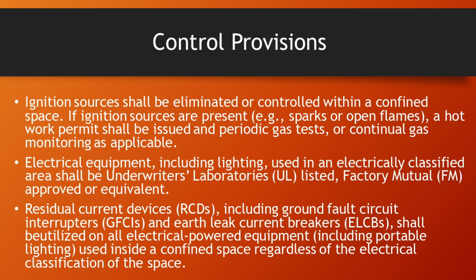Residual current devices, RCDs, including ground fault circuit interrupters, GFCIs, and earth leakage circuit breakers, ELCBs, shall be utilized on all electrical-powered equipment, including portable lighting, used inside a confined space, regardless of the electrical classification of the space.